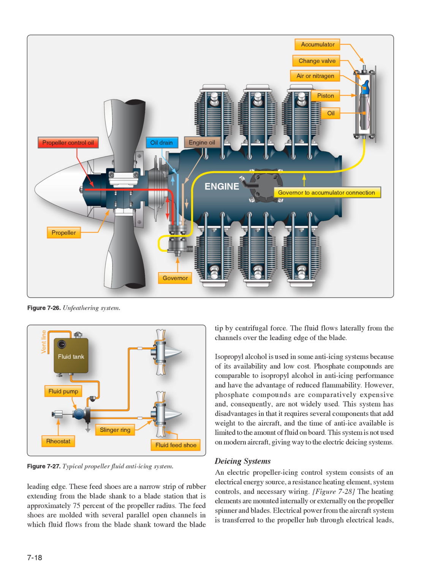This system has disadvantages in that it requires several components that add weight to the aircraft, and the time of anti-ice available is limited to the amount of fluid on board. This system is not used on modern aircraft, giving way to the electric deicing systems.